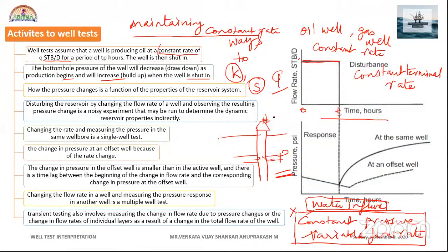So we are talking about the bottom hole pressure, the pressure acting at the formation, and it is not always equal to your reservoir pressure. The initial pressure is always greater than your bottom hole pressure, because if this condition doesn't exist, the fluid will not flow into your wellbore. That is why we have to make sure that this relation always holds.